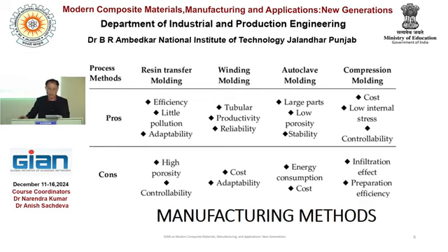That means a large part can be cured properly, very low porosity is possible, and property stability can be expected. But energy consumption is too high because it has a huge inner space to cure. Heating and cooling consume too much energy, and that means the cost is very high.